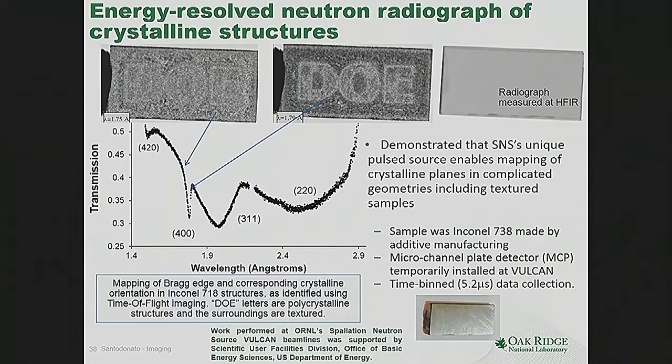If your crystal grains are aligned, then the Bragg features are going to be enhanced there. Therefore, the transmission is different, and that's ultimately all we see with a neutron imaging instrument experiment: transmission. So we have to relate the transmission back to either composition, density, or in this case, crystal orientation. So that's kind of the next level.